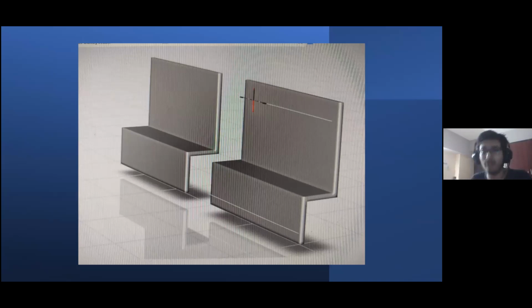We made two lines. As you can see here, there are two white lines, one near the foot and one near the head. The white line near the head goes past the three sections of the seat: the window seat, the middle seat, and the aisle seat. It goes near the passenger's head area and near the passenger's foot area. So we have used this to capture the thermal comfort in all parts of the passenger, near the head and the foot.